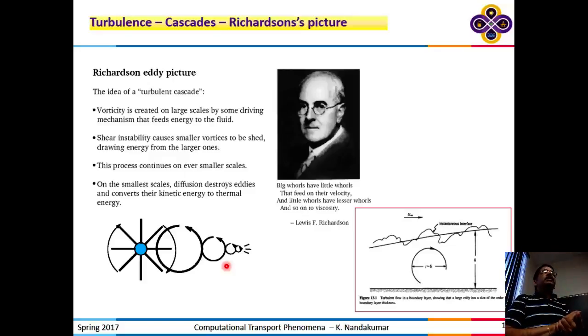What does the large eddy do? From an earlier point, we talked about mixing, right? So there are two parts of mixing. One is dispersive mixing, another one is distributive mixing, right? So the distributive mixing takes material from one point to another point and advects it. And those are done by these large-scale vortices.